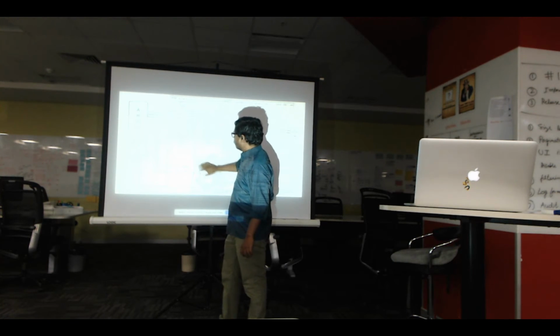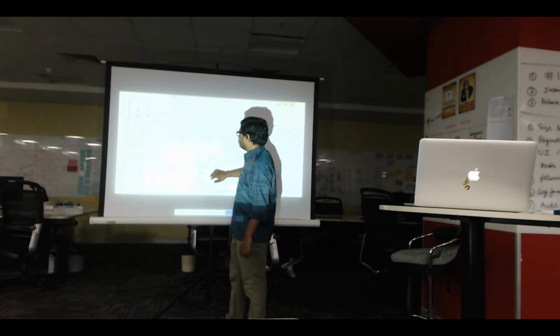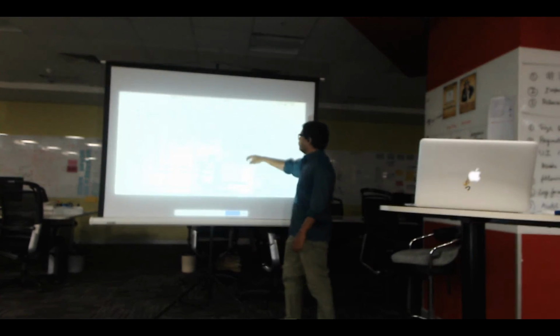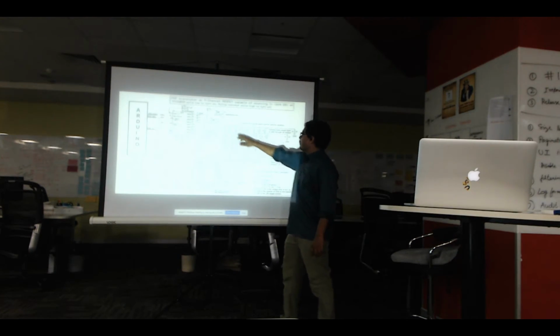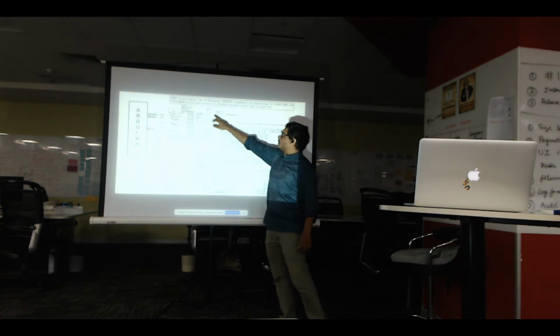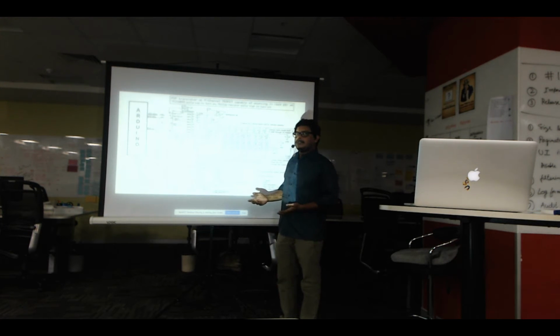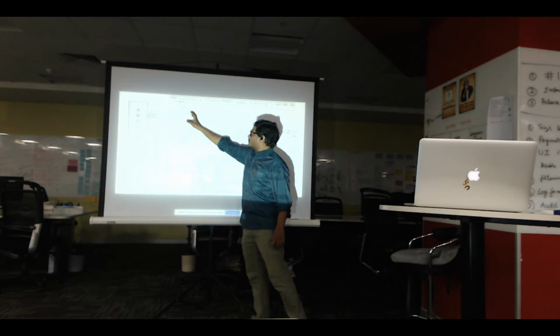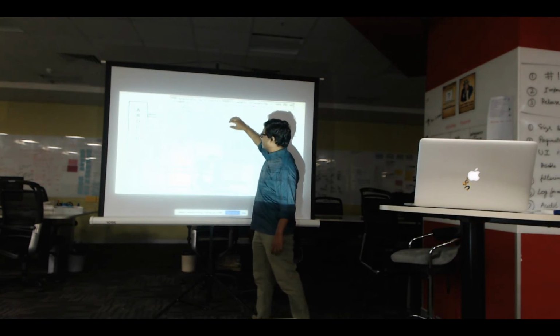Here we see the two shift registers which are connected to it, and here you see the LED grid, where this represents the row and this represents the column. And since each row has many LEDs, we decouple the shift register from the LED circuit using a transistor or MOSFET.